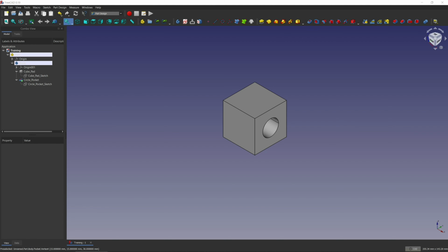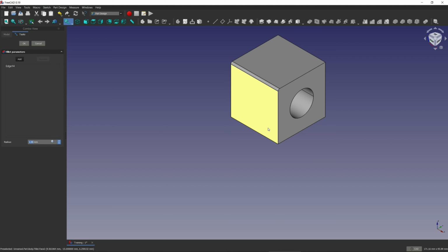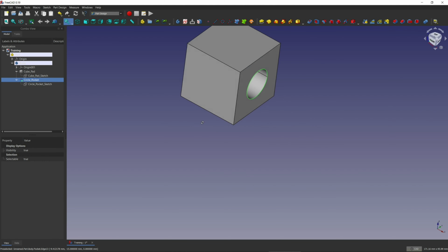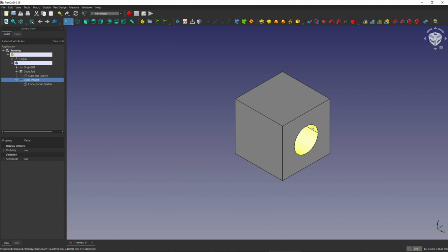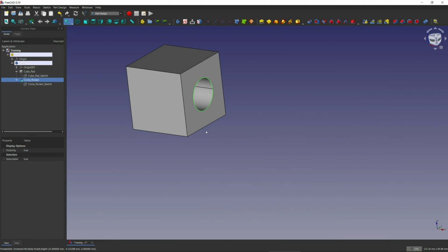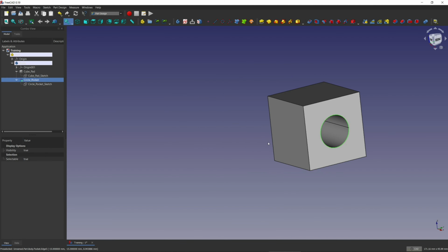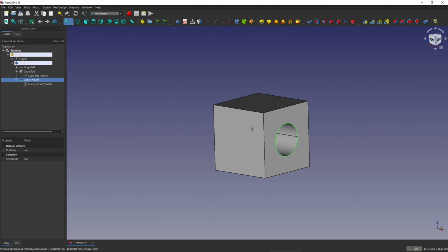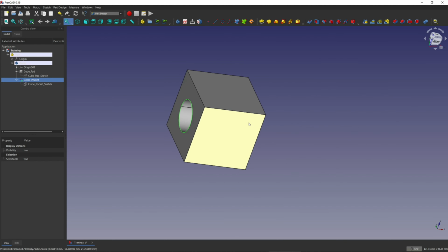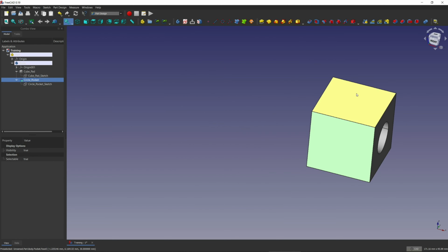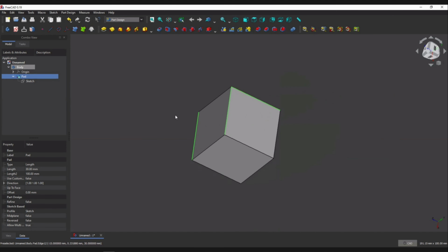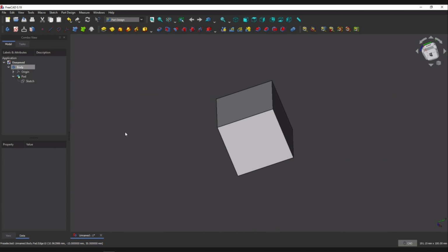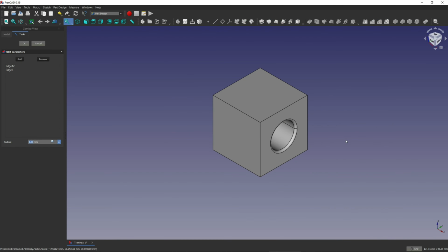And one of the best ways to avoid this, rather than using the horizontal expansion slicer settings, is just to chamfer the bottom edges of the model, which if you're designing your own model is very easy to do, but if you're just downloading a model from somewhere, it becomes a little bit more complicated. So that was the next thing I asked, and where you can see on the screen here, we can select faces, we can also select edges, and then we can use the Fillet Tool, wasn't it? Yes. The Fillet Tool or the Chamfer Tool.